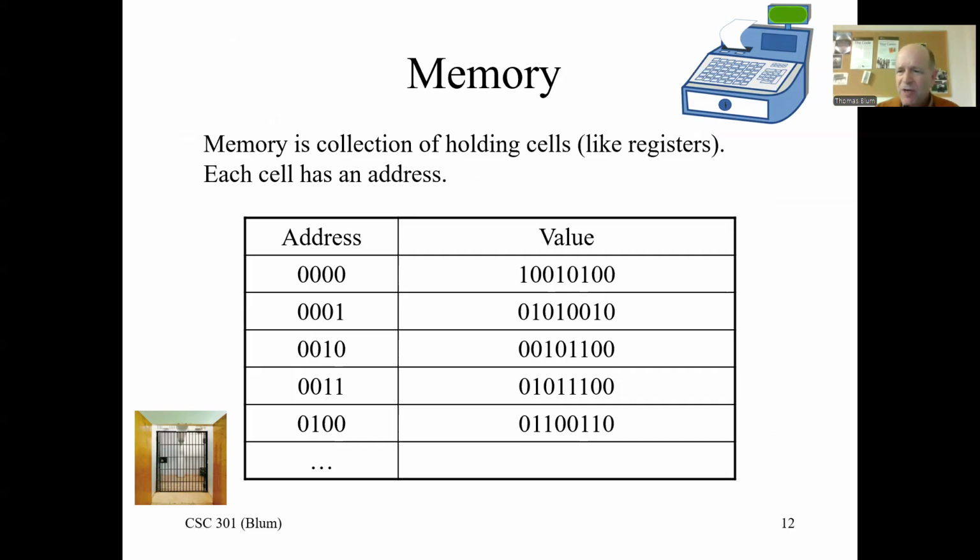So RAM is an addressable set of locations. We talked about a register as something that just holds a sequence of ones and zeros, but then we have a set of these registers, and we figure out a way to identify each one, and we call that addressing. We address them. If you supply the address, then you have access to that value. And that's what we mean by random access. Like at random, I could supply you any address and get the value at that address.